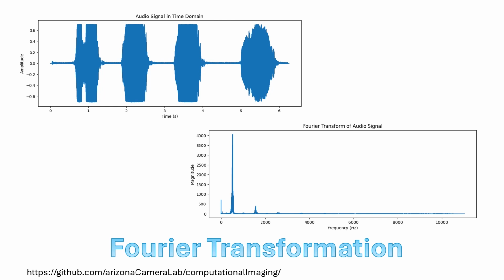Now we can't really see much on the plot of the sound wave at the upper left because the MP3 format stores 22,000 samples per second, even though there aren't actually 22,000 samples stored in the recording. But we have these 130,000 data values, and when we look at the trace, we don't really see those resolved. We do see peaks in the Fourier transform, though, so let's try to understand where those come from.